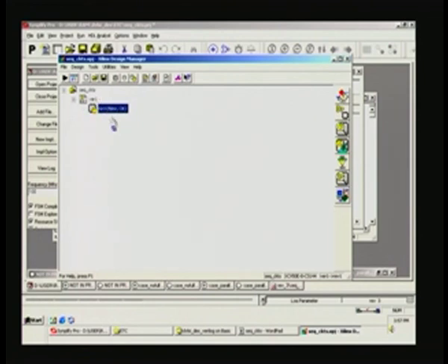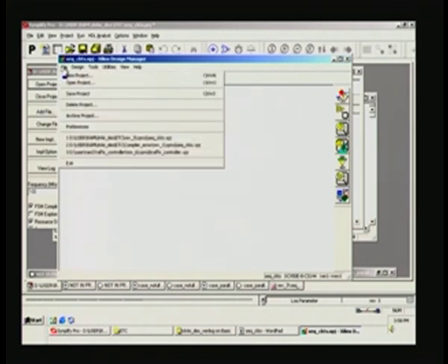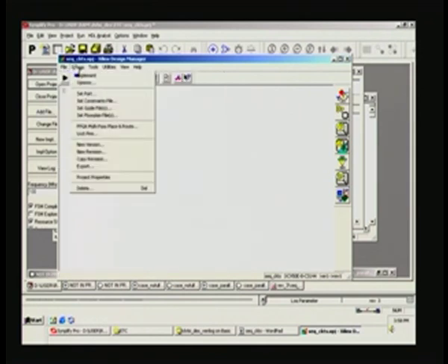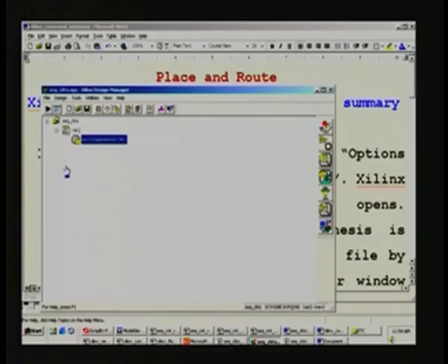And now the next step here is, the place and route already knows that the input file is sequential circuits .edf, and this will be taken as the input file and processed further. So, what we have to do in order to do the implementation is, there is one arrow here, just click on that, it also says implement here. Otherwise, from file also I think you can have it, or in design you can have implement, that also you can have.